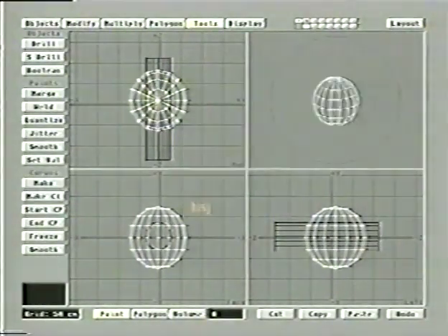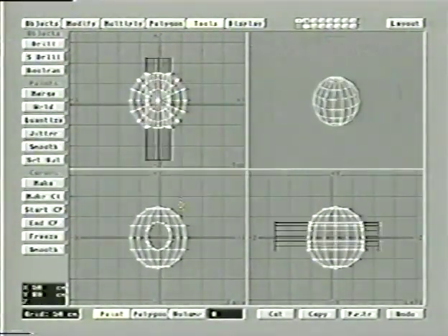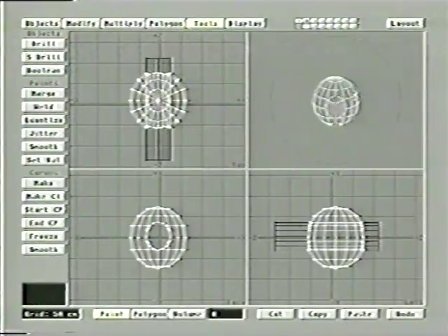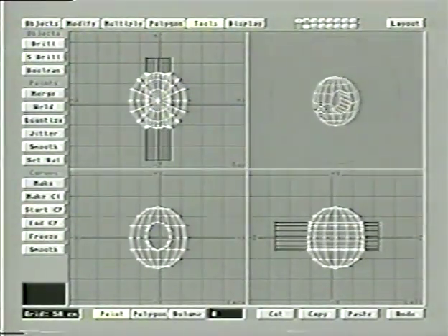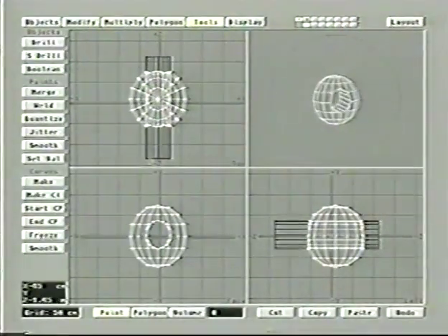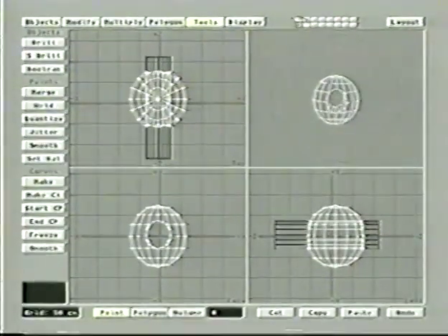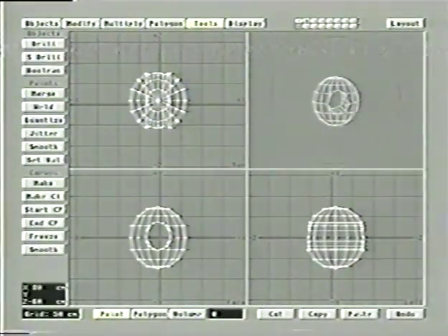And when we do this, it ends up pulling the disk out, and you see we've got a nice clean hole right through the sphere. Now, you'll notice that we can still see the disk, though. This sometimes throws people. We can still see the disk, of course, because it's on an inactive layer that's still selected. If we get rid of the inactive layer just by reselecting our active layer, let me click on layer 1 again. You see the disk isn't really there.